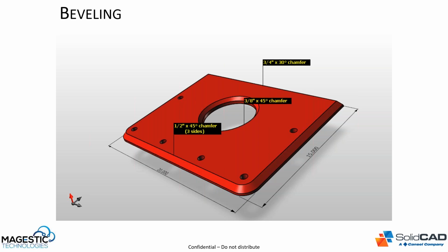So we also do some different optimization for the cutting on the bevels as well. We'll do some quarter cutting optimization for some of the bevels, in this case where we'll lead out of the shape, do a loop and then come back this way. And we'll program that toolpath optimization automatically for you.